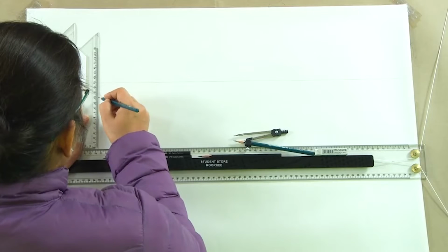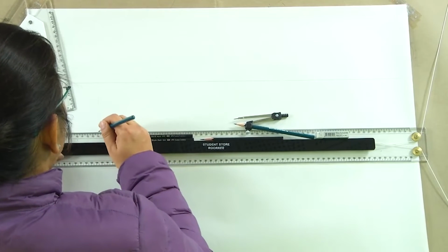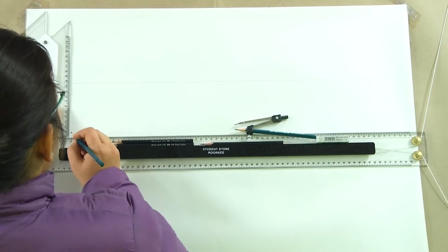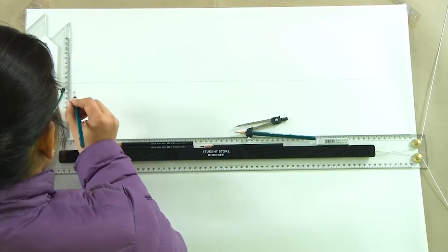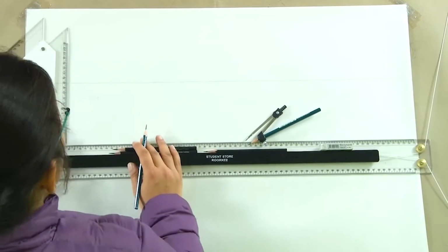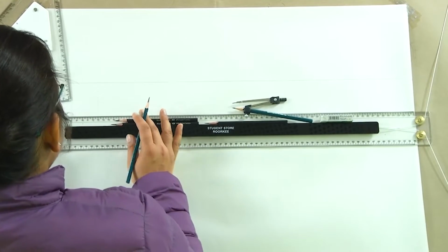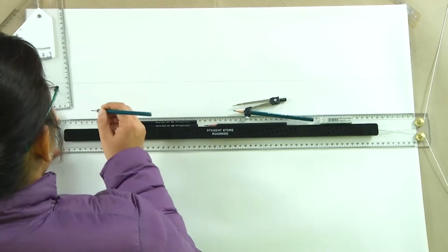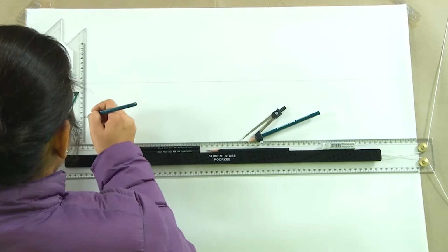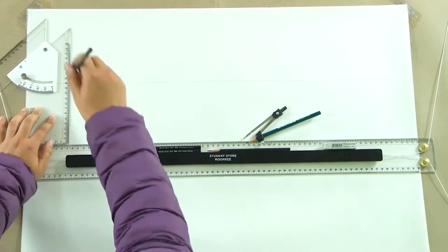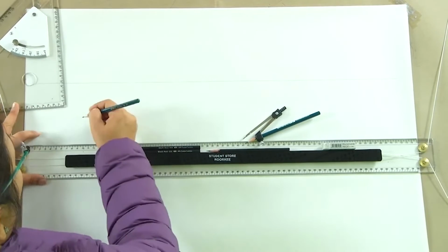It says that it is a rectangular prism which is kept on the ground. If we look at this prism in isolation and forget about the cylinder, what do we see? We see the base, the size of the base. Here I am assuming that this base is 7 centimeters by 5 centimeters, a rectangle. So we just draw this rectangular base, and the axis for this rectangle is going to pass vertically through this point. That is where we will see the axis.